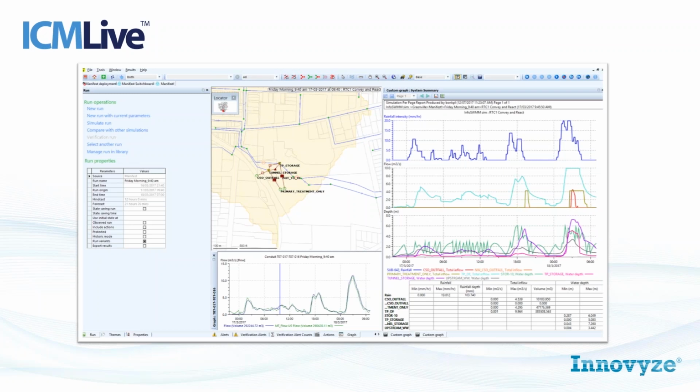So yeah, and the particular model has been used to detect blockages, avoid spills. It acts as a technology for safety for construction crews if they're operating on the network, to warn them of an incoming event or to establish a bypass alternative. It's utilized to prime pumps and RTCs for incoming events. It gives a sense of live availability of storage in your network.